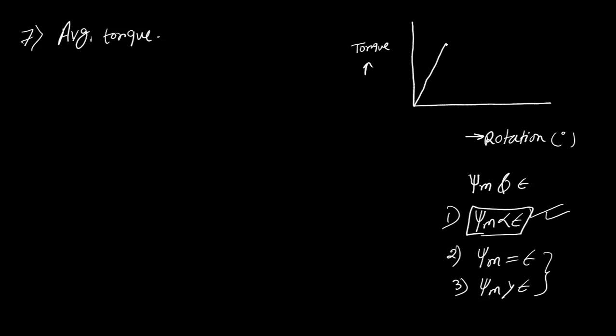So then this torque will come down because after a certain angle there will again be no engagement of teeth with the workpiece. At that time also we will have zero torque. Then again, up to a certain time there will be no engagement, and once more teeth come to engage with the workpiece, it will again create some torque and once again come to zero, and this way the diagram will continue.